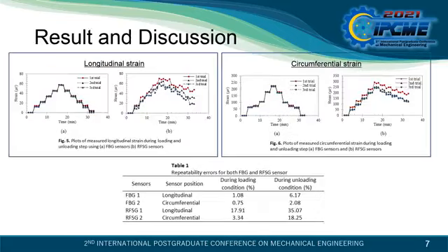In this experiment, the pipe was internally pressurized by using tap water and performed under a series of pressures ranging from 0 to 5 megapascal, with a maintained temperature at control room temperature of 27.5 degrees Celsius. The internal pressure is increased with a step of 1 megapascal and maintained for at least 3 minutes in each step. So the wavelength shift of the FBG sensor is recorded from 1 to 3 minutes for each step to reach its stable condition.